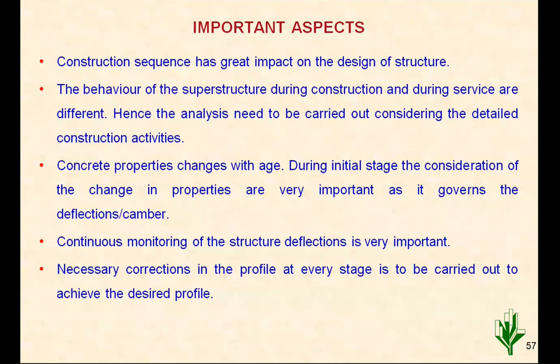And once it is tuned, in these 2 or 3 projects we found that more or less the theoretical assumptions were matched at site. And still some differences come. So during analysis itself, some extreme value consideration has to be done. It is called sensitivity analysis. Sometimes you will find that deflections are more than predicted, sometimes lesser. So some engineering judgment has to be put. What is the effect on overall structural stability because of some extreme cases? That is called sensitivity analysis. And if that is done, then probably there should not be any issue as such.